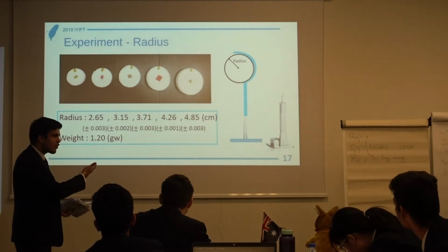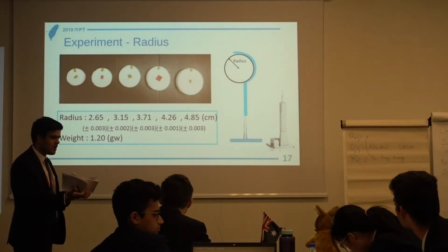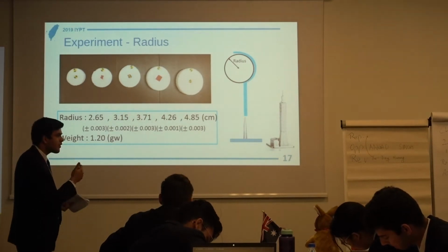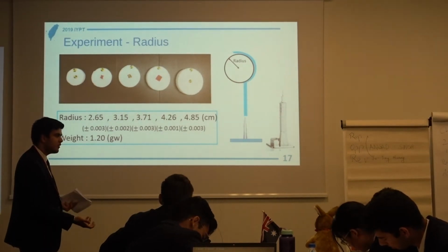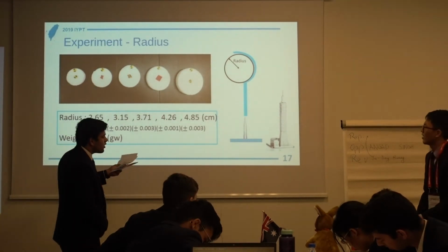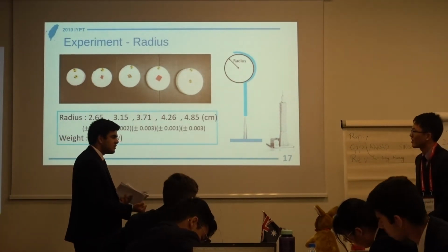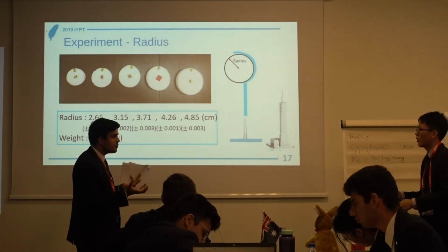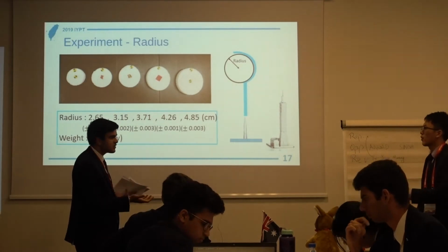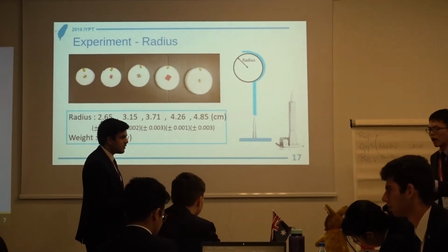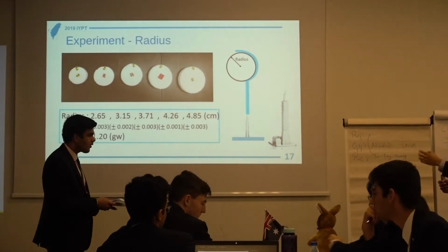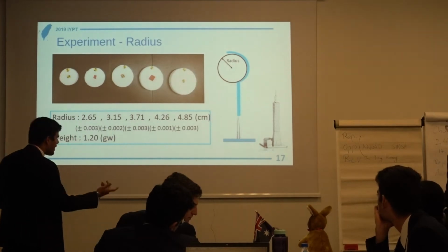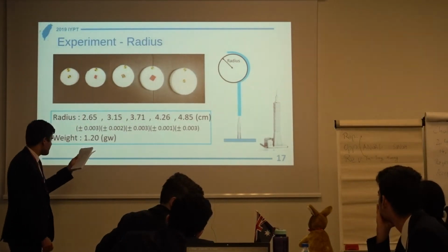So a lot of your graphs should technically have a different angular velocity, it shouldn't match your theoretical. Then why do you think some of your theoretical values work with the experimental? The moment of inertia of your mass changes, yes? Yes. But you acknowledge that? We add a mass on the center of the disk. But your equations use the assumption that there's an equally distributed mass in the disk, yes? But that is not the case, of course, you've admitted that. Okay, then, I don't agree with that, but I will move on from there.